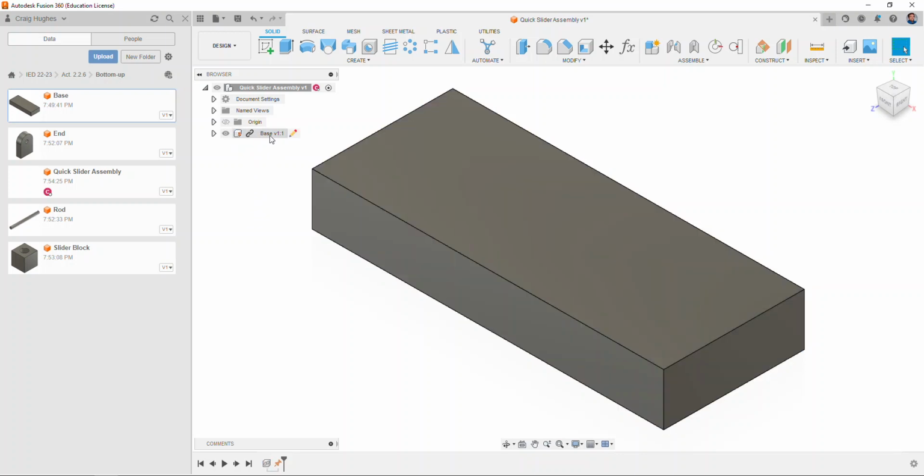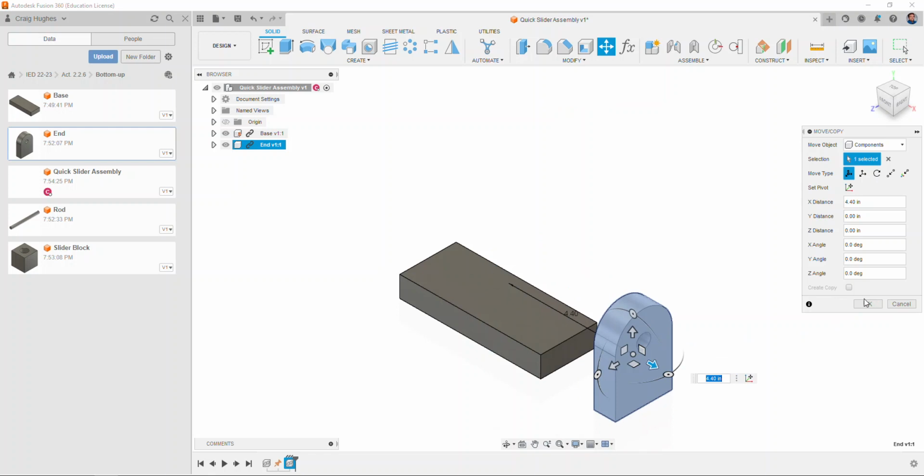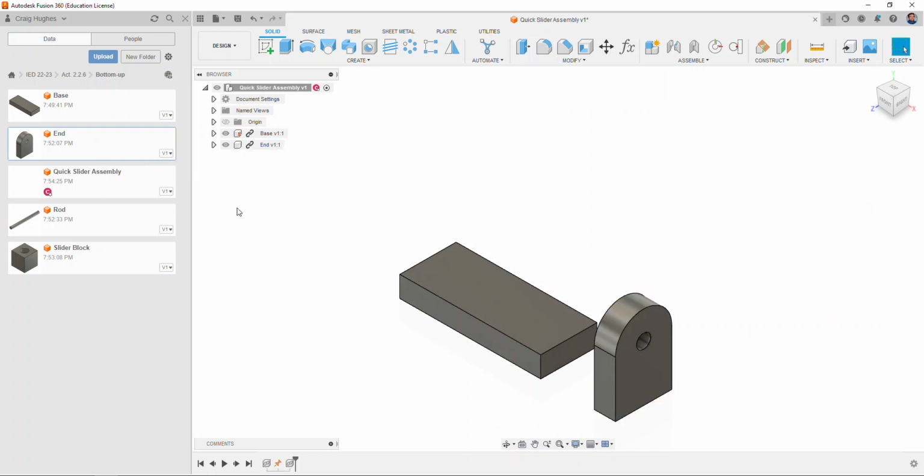This is also going to show the base component. There's the single cube. That means it's there. If you look at the top of this one, this changes from a single cube over to multiple cubes. So this is showing you that we've got more than 1 component existing in this file, and we will as soon as we insert some of the others. So I'm going to insert into current design. Go ahead and drop an end component in there, and I'm going to do that one more time.